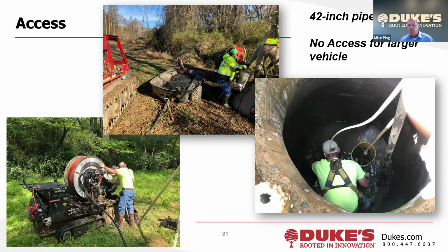You may have to go maybe one time is enough. It may require lots of times. Typically in our industry, it's normal to talk about 3 full passes being included in light cleaning. Anything more than 3 passes is generally classified as heavy cleaning and usually hits a different line item.